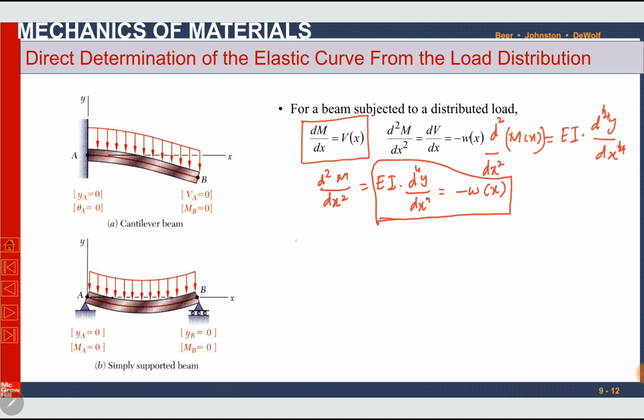If we integrate it for the first time, it will be EI d cube y by dx cube. This itself is equal to shear function, and the right hand side can be integrated as integral of load plus C1. C1 is constant of integration.